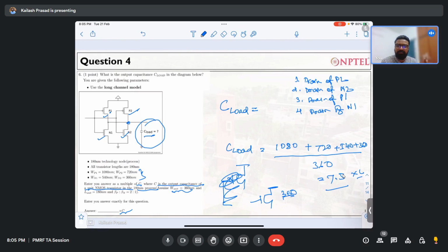Please note that this is extremely important, because in coming lectures we'll be discussing logical effort. Suppose you are designing a very large circuit, say a processor. You don't go and size each of these transistors; a tool does that, and that tool is called a synthesizer. But if you want to do the same job yourself, how do you do that?